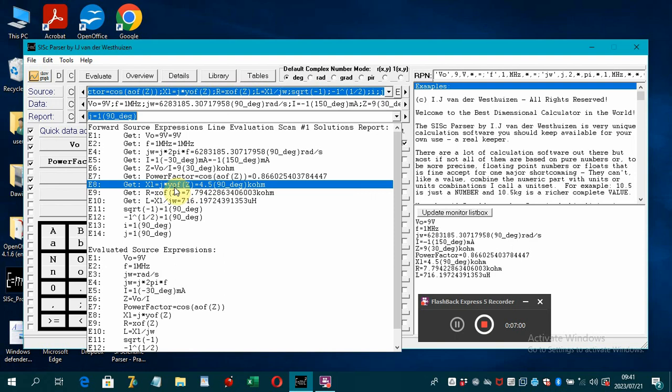Now, Y of always gives you a value on the x-axis, but because XL is imaginary, we must multiply it by J or I. You can use I also, but in electrical engineering we use a J, because a small lowercase i can denote instantaneous current. We use I for current, and a small lowercase i can be very confusing in electrical engineering. So the J is preferred to denote the square root of -1, and so that is just a square.